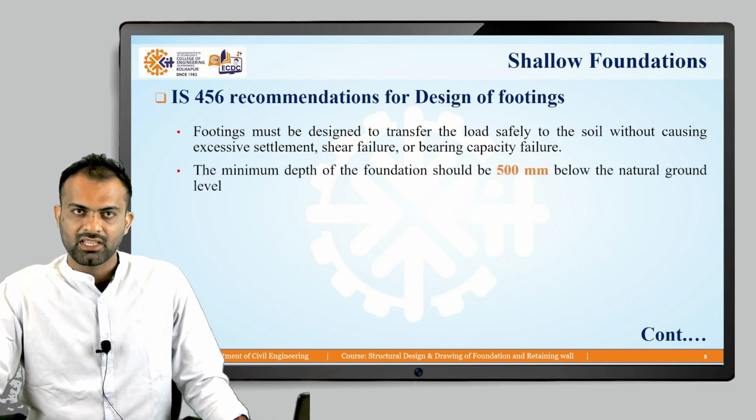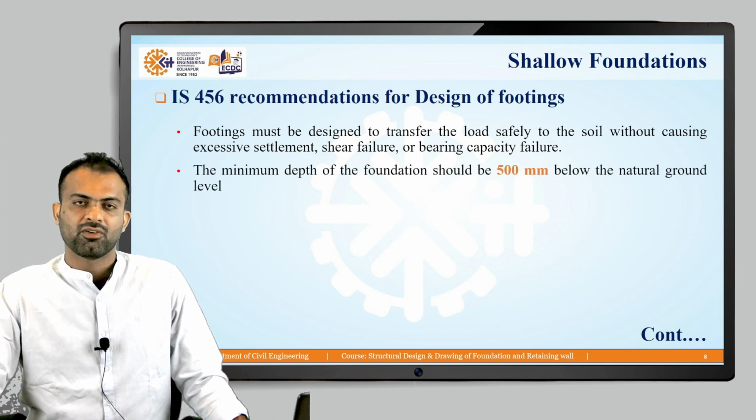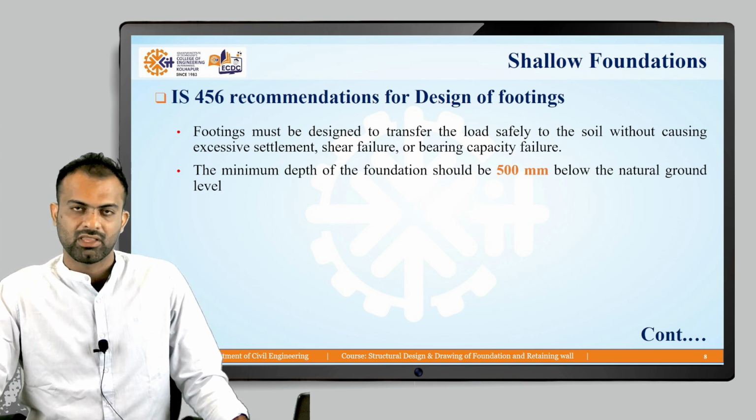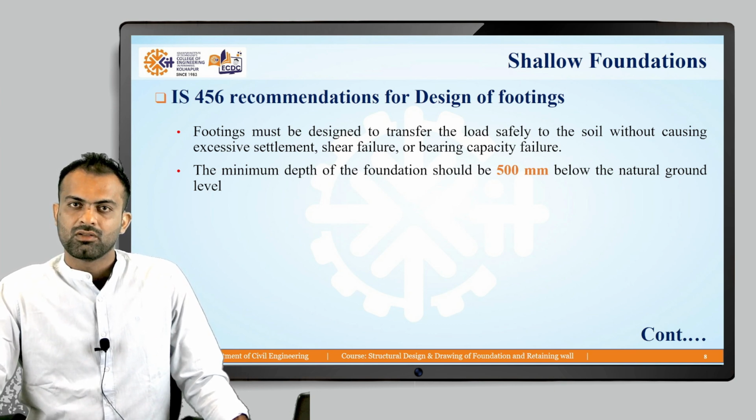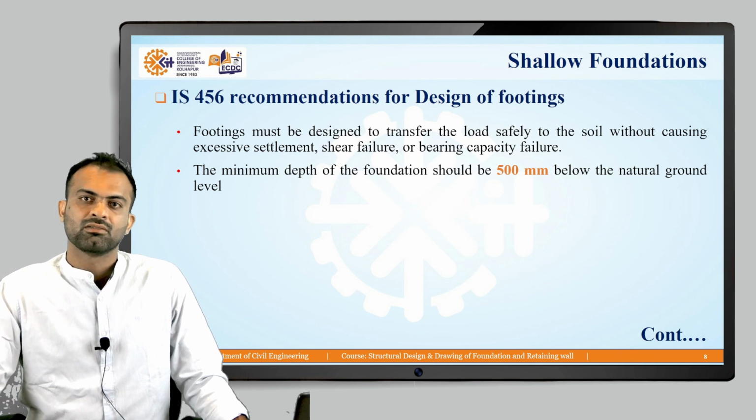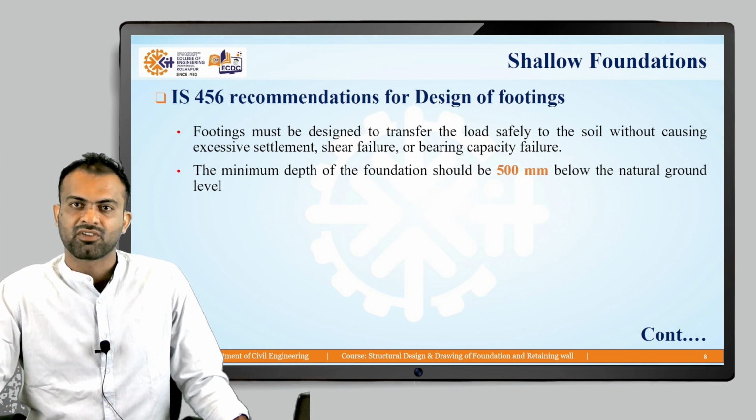And the second one is the minimum depth of the foundation should be 500 mm, that is 0.5 meters below the natural ground level. Even though we find a good rocky surface, we have to keep the foundation at least 0.5 meters from the ground level.